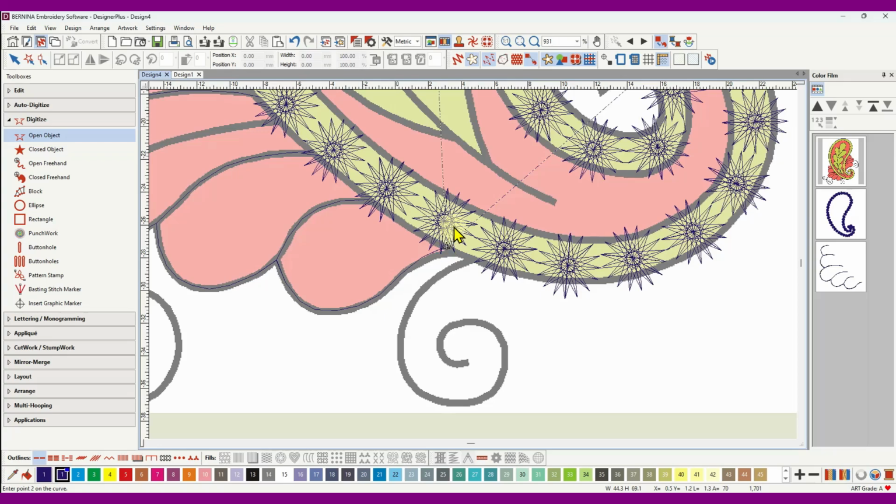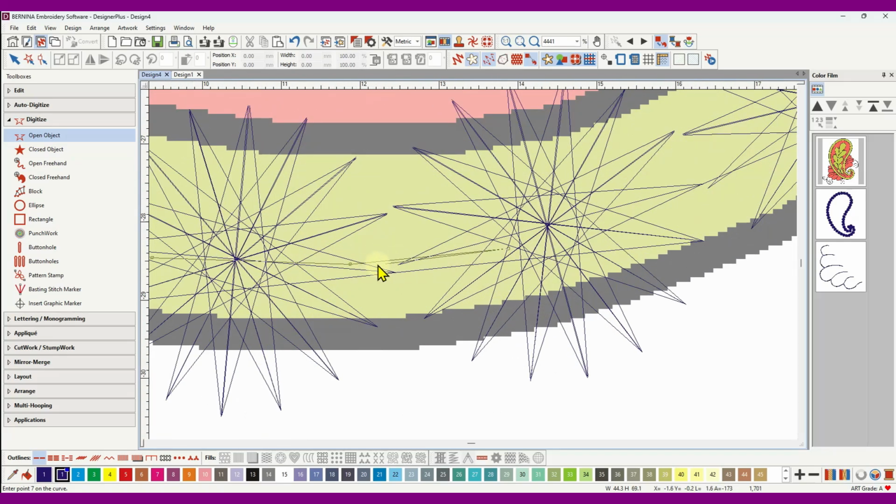I'm going to go into this Candlewick, and I'm going to try and cross over where the points cross and follow that around. Sometimes you might have to click halfway into the Candlewick to change your angle to get through, but basically, I'll just zoom in, I'm trying to avoid this sort of thing where I'm going to get a stitching line between gaps. So I'll just backspace to get a better angle on that. I'll do it about here, left click,